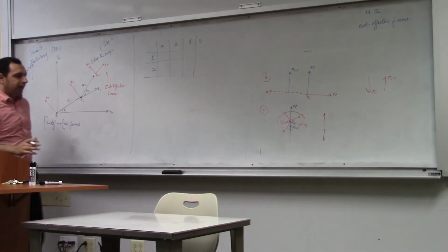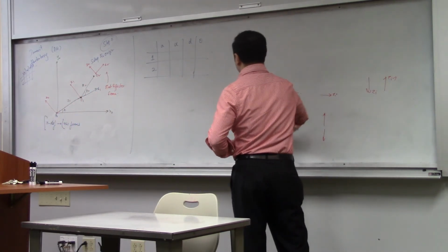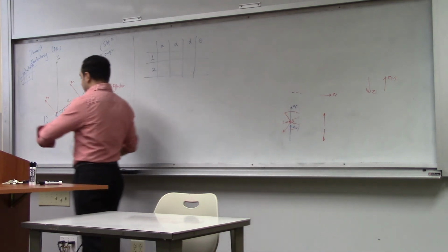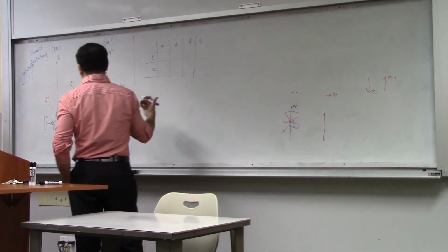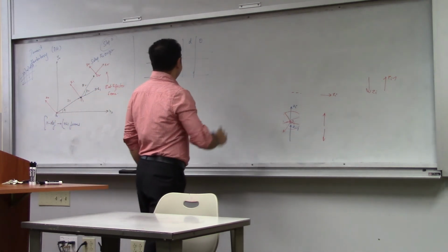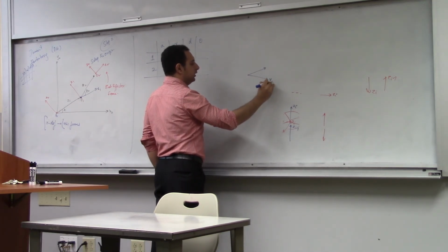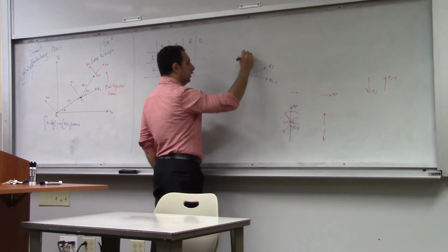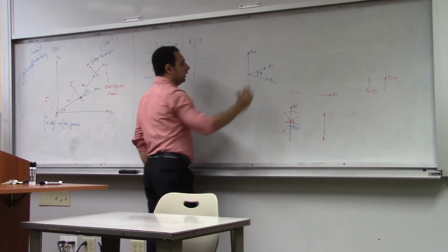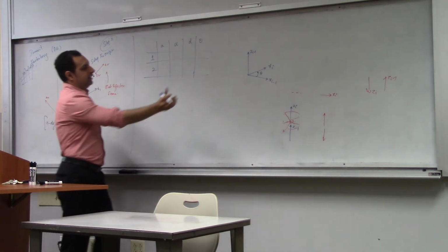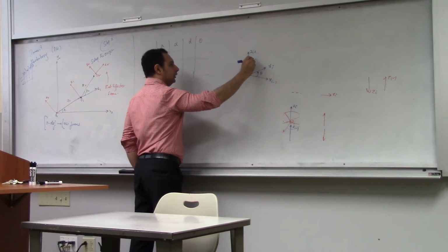Now in this case, there are two angles. The angles are really important. The distances are fairly easy to measure, so it's not a big deal measuring A and D. The angles are a little tricky. So when you look at the original diagram I gave you, theta is the angle measured between xi and xi minus 1, along zi minus 1. You measure it about zi minus 1 from xi minus 1 to xi, like this. Okay? This is theta.